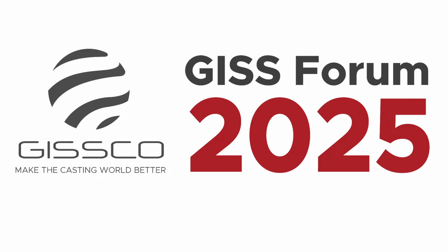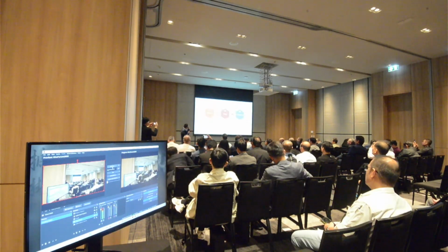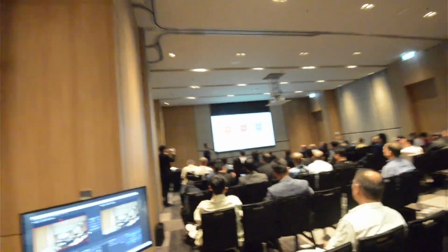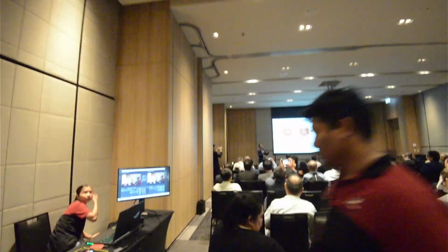First, this is my content. We know there are three processes in castings: melting, filling, solidification. If you are a foundry man, you focus on these 3 processes. In the melting area, you need clean metal: no oxide film, degassing, hydrogen, everything, and the right chemical composition. Once you have clean metal, the next step is filling your cavity, no matter whether high speed or low speed or gently filling.